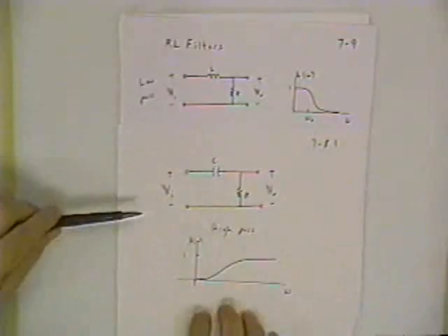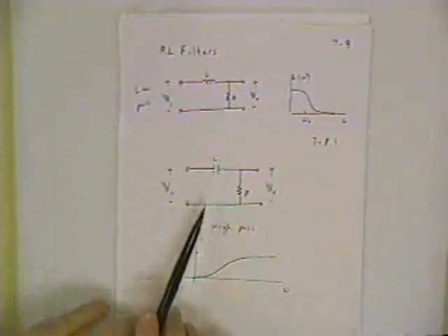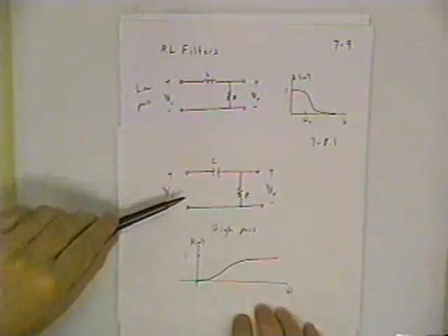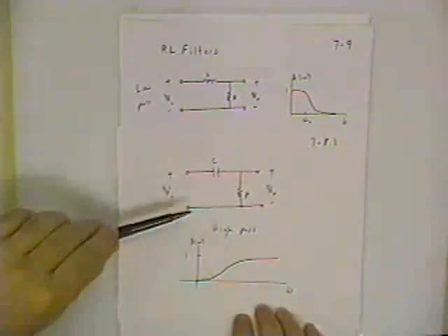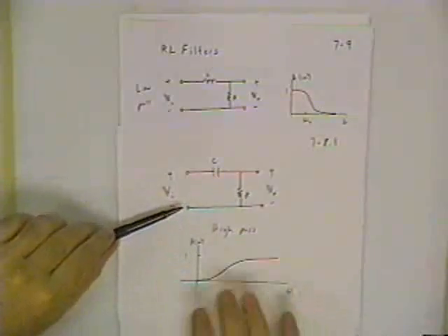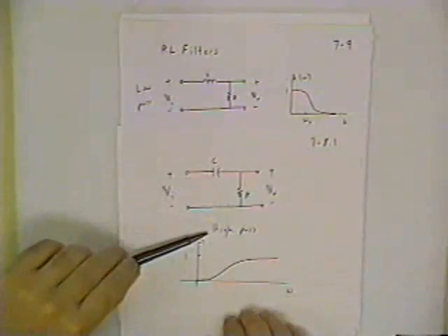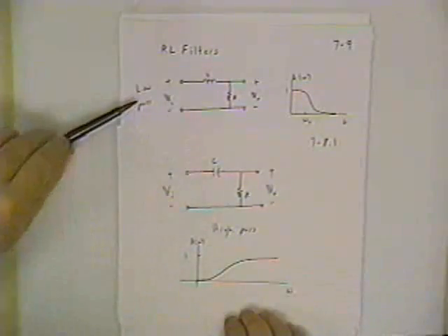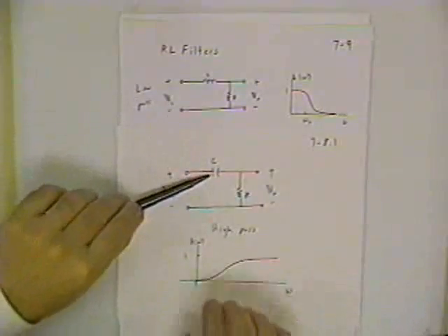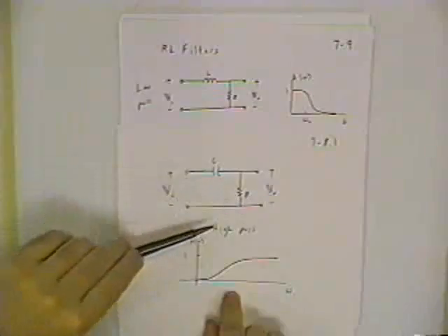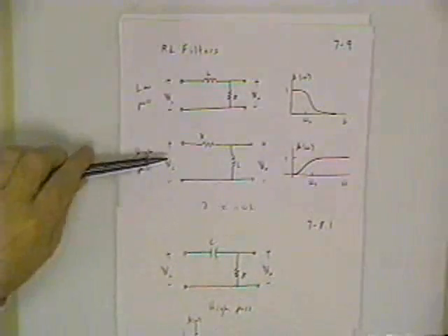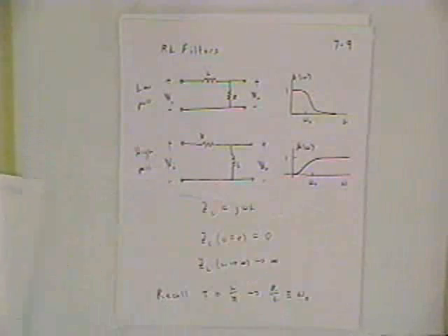And that's real useful because all it means is you just have to figure out one of these first order filters. Let's say I write this one out and I figure out it's a high pass. And now I know all the other three, because if I switch the R and C, I get a low pass RC. If I replace the capacitor with an inductor, I get a low pass RL. And if I then switch so that there's a resistor up here and an inductor, then that's my high pass RL, just like I showed you here. So for these first order filters, all you really have to do is apply the voltage divider to the first one, and then remember all the others just by the arguments I just made.